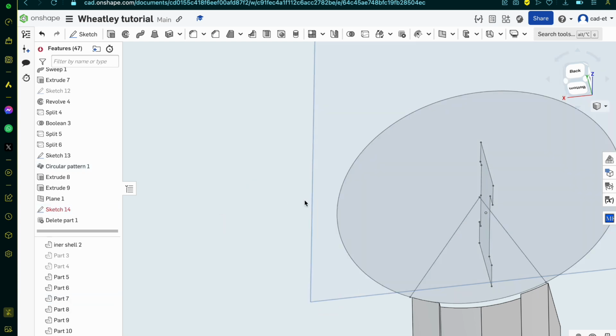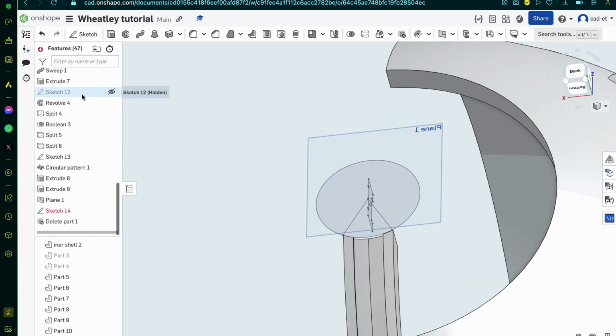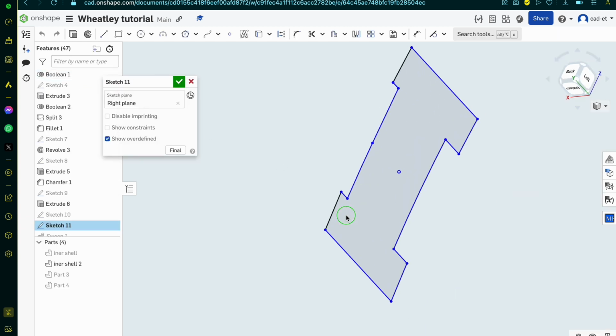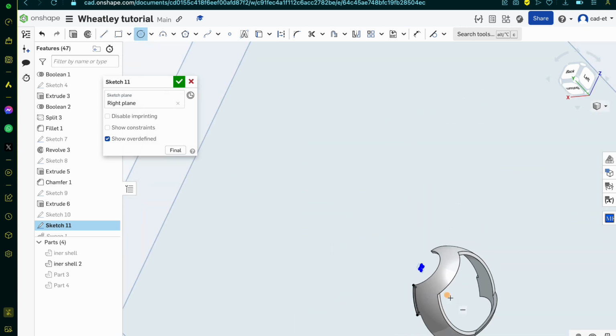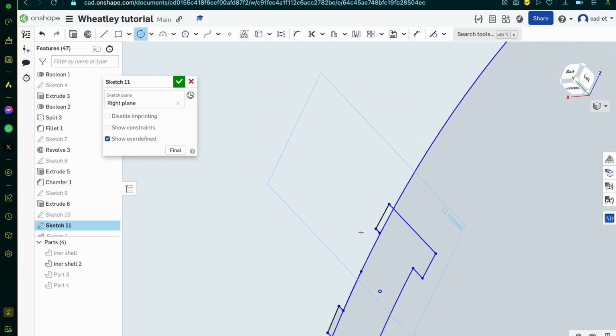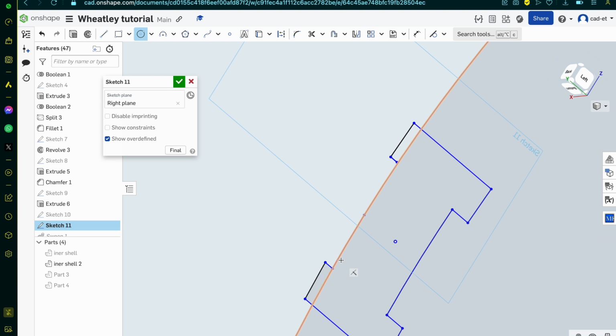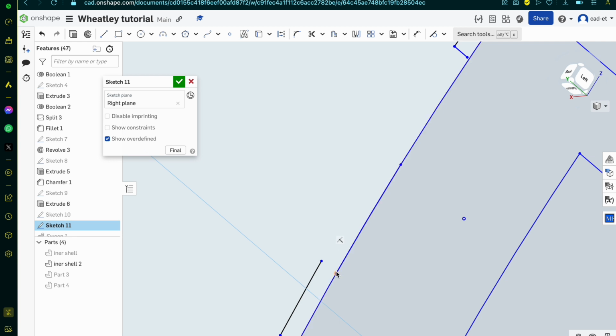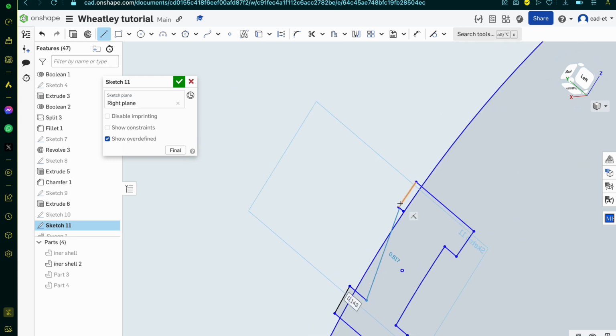Now I need to trace down where that comes from. So hang on. I'm now just chasing errors. I see it now. That's a straight line where it should be curved. I must delete the curved line that intercepts there by mistake. So could delete this line. Draw an entirely new one here. Now we'll go trim again.